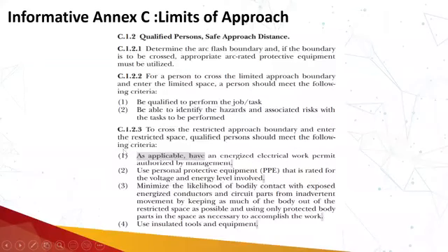As we move on, we will see that the energized electric work permit is not a mandatory requirement for some types of jobs. For example, if you are performing thermography, testing, troubleshooting, or measurement, those tasks are exempted in 70E from completing an energized electric work permit. Whether you should do an energized electric work permit or not, we will discuss when we get to modules 3 and 4.